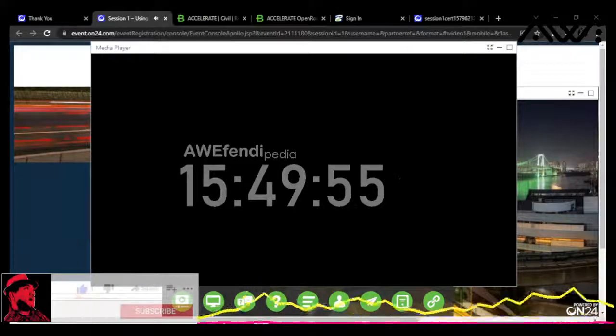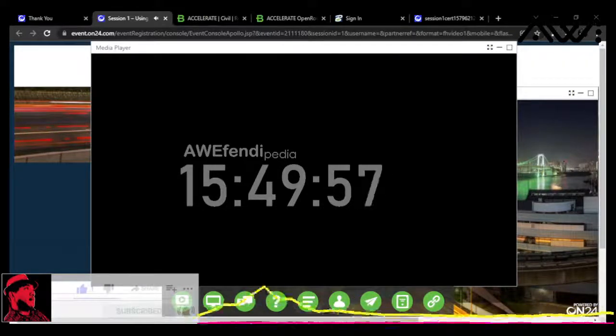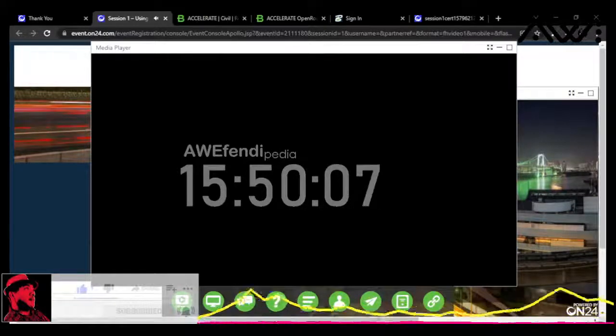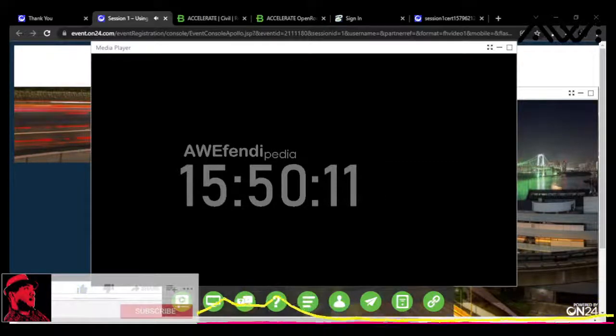So it's important now that you choose the 3D seed file. Our survey information when it comes in is 3D. It's going to be drawn in 3D. It's going to be annotated in 3D. And so that's the file we're going to choose. And I'm just going to name the file Survey and then hit Save. And that file is going to be created in the background. OpenRoads is going to load it up. It's going to load all of our preferences and workspace information that we chose up here.